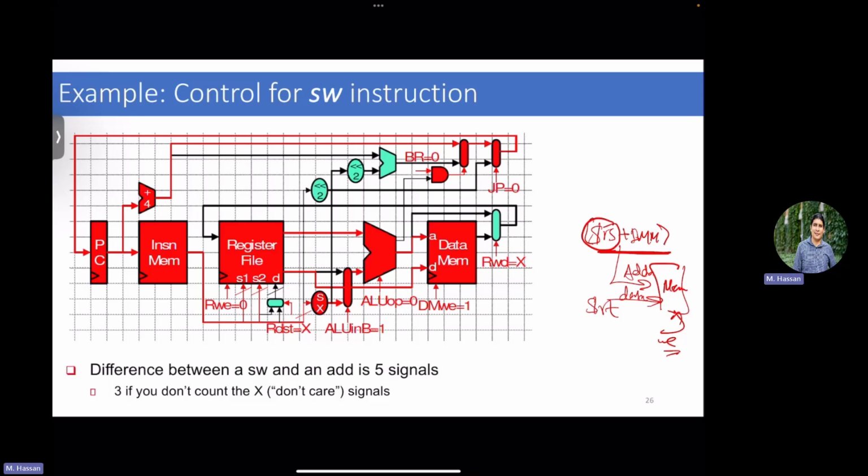And then I need to take that path, but this path is just a wire, so it's always there, right? So I don't need to worry about it. And then I'm not really reading anything from the memory, so I'm making this one don't care, because again, this path will go eventually to write to the register file, and I'm disabling the register file write. You can observe that we're trying to make our logic as many don't cares as we can, because remember from 2DI, this will simplify your Karnaugh map, right? This will give you more possibilities. It can be either 0 or 1, you don't care. In case of a store, you don't have jumps and you don't have branches, right? So you should be fine.